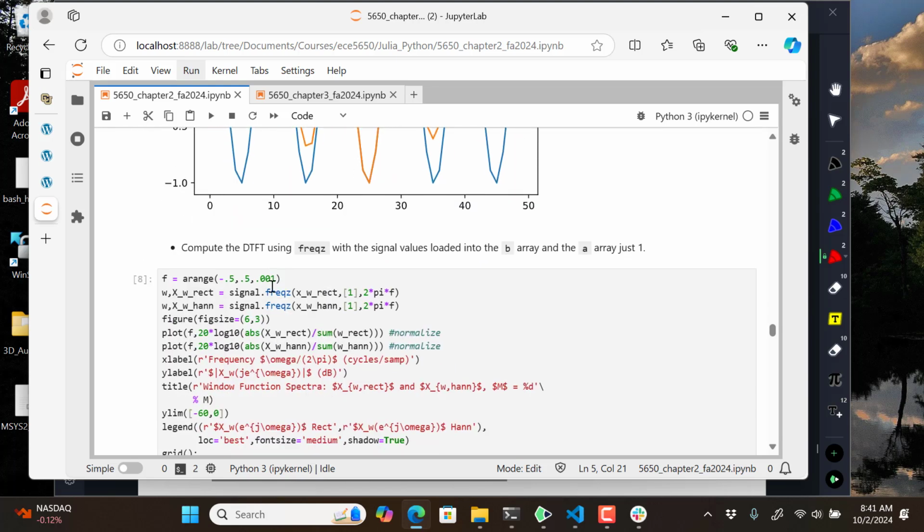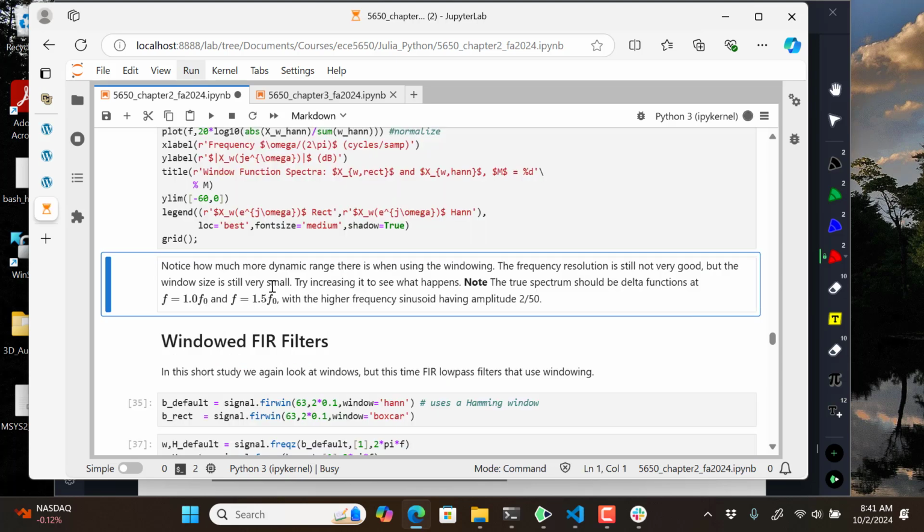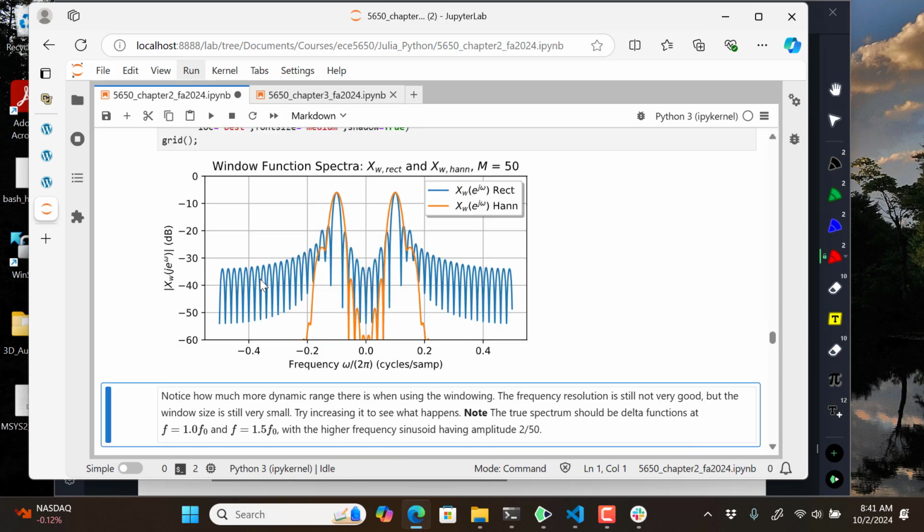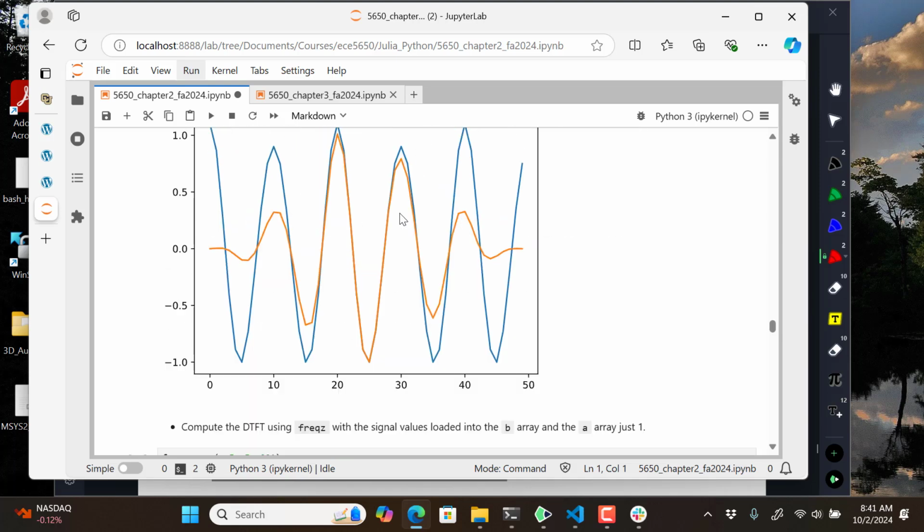And if we go here to the frequency domain, can you tell that there's another sinusoid in there at 1.5 frequency? It's trying to push its head up, but it's getting clouded by the backwash from the leakage from the dominant signal in here. If I brought it in closer, this little blob here would fall underneath that big peak, and it would be totally under its shield and not be seen. So the solution here, though, is just to say we're going to have more samples.